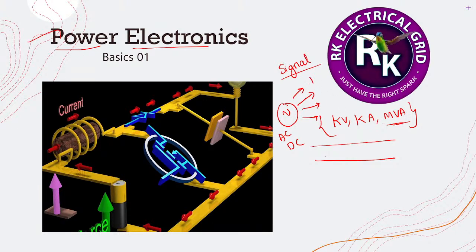Can you directly use a simple diode? No, sir, I cannot use a normal diode. Why? Because this normal device, which you might have read about in analog electronics, has a switch rating of 0.7. If it is turned on, its cut-in voltage will be only 0.7 volt, not kilovolt or kiloampere. You can't even compare this voltage with our power ratings.